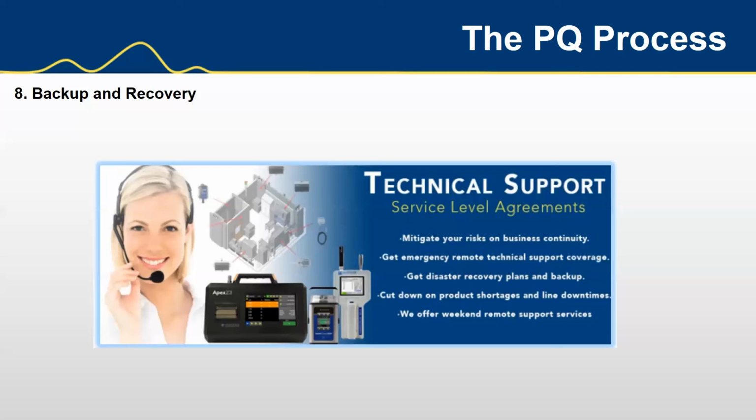continuity. Does the EMS or particle counter vendor have remote technical or on-site technical services available? Are they 24/7? Are you in compliance with GMP Annex 11, for example, computerized systems? Do you have spare instruments and parts to minimize downtime? Is the system a plug-and-play setup? How much manual technical support do you need? Do you have service level agreements in place? What is the escalation process? Before going live, you'd want to address all of these critical questions and validate the process.